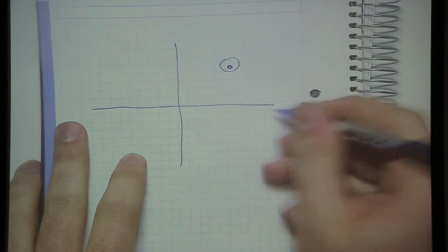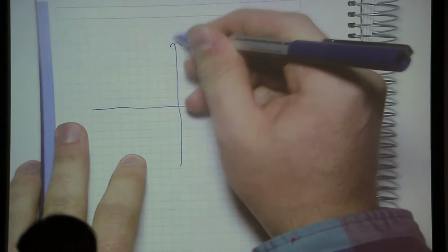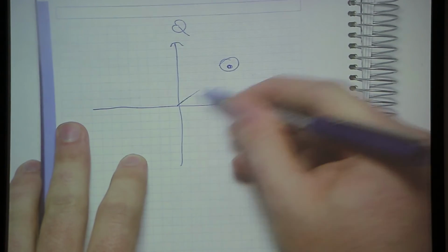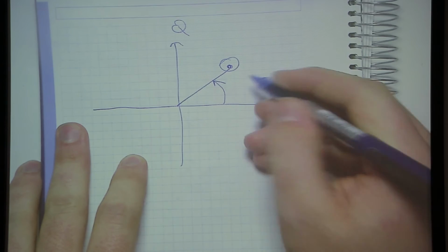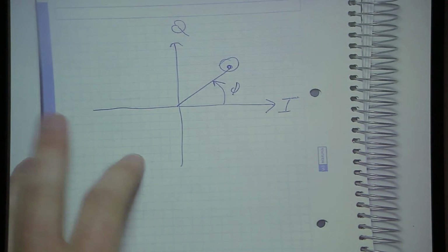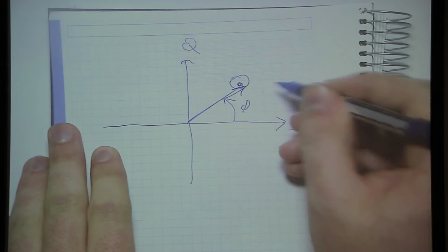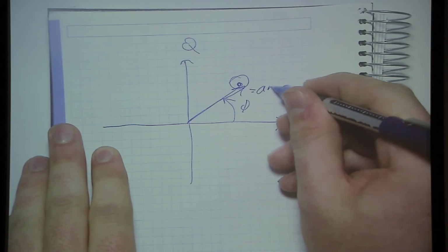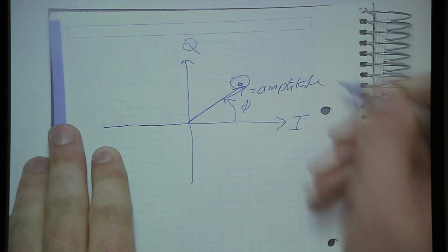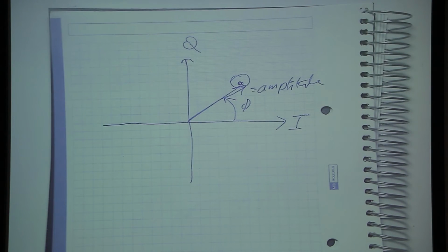Here's our point that we receive. If we measure this angle, that is the phase of the current sample. And if we measure the length of this, then that's the amplitude. Which means at any moment in time, we know exactly what the phase and amplitude is. And now in our software, we can very quickly work out, okay, so right now we're at this phase, a few minutes later we're at this phase. And that naturally leads to most ways of processing